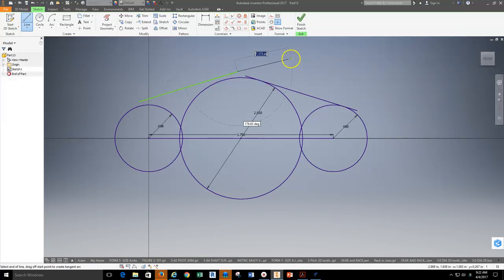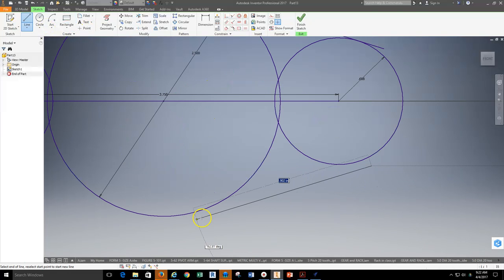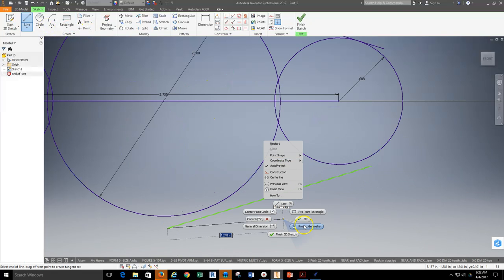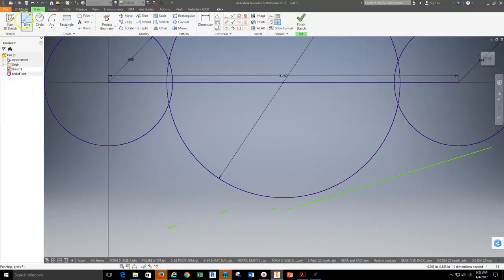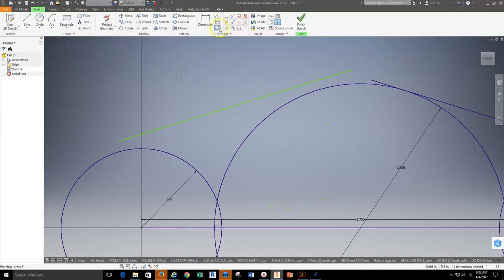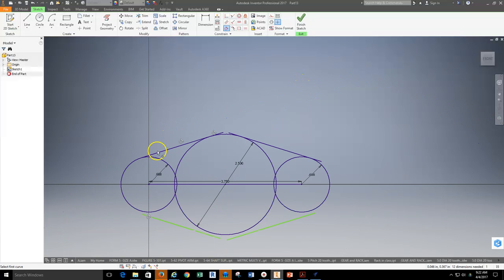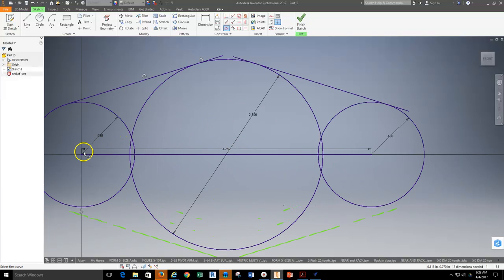I will first go ahead and rough in some lines. So I have them, and I'm going to use that same constraint tool again to set up the relationship. I'm doing this very specifically because I do not want to have additional constraints placed without my knowledge. I'm going to grab the constraint tool, grab my line and the circle, and then the line and the circle. As I'm doing this, I'm also making sure that these circles aren't moving to the line.